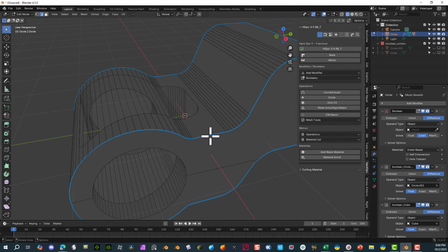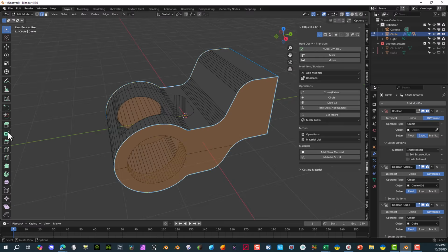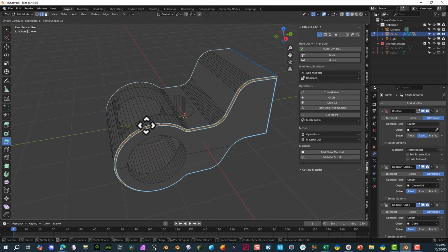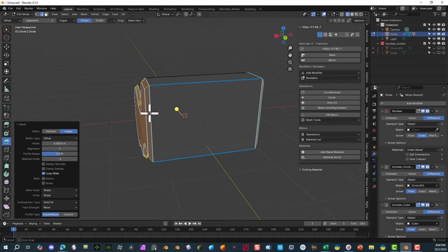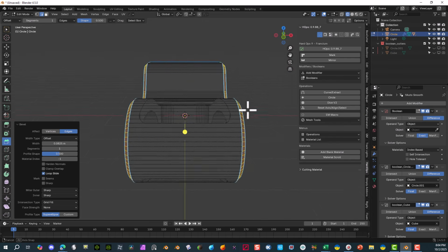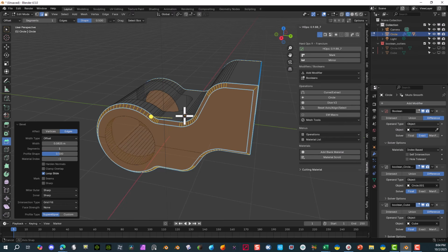Okay, so now you can see the lines. See how it's nice and blue around? That makes it a sharp edge, so it helps control the look. And we can go in now and try to add in a nice bevel. So I'm selecting the edge here, just to make it look nice. I'm good with that much distance on that bevel.